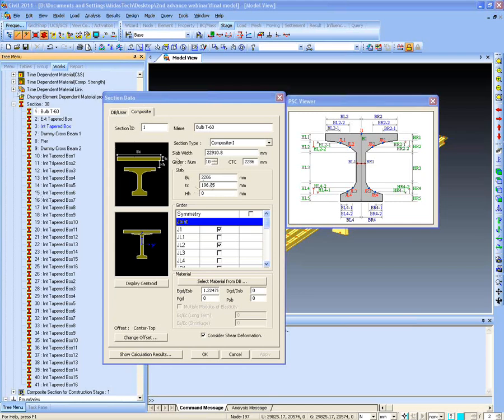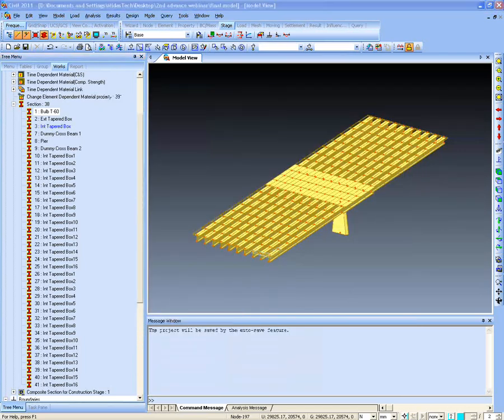for the grillage model, the user must enter the same data, that is the data for one section only. So slab width would be the width for a section and the girder number will be 1 having CTC 0. I hope it answers your question, Mr. Salius.